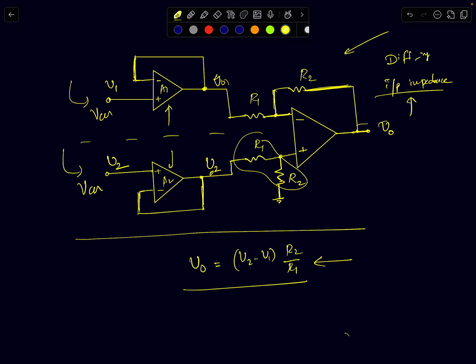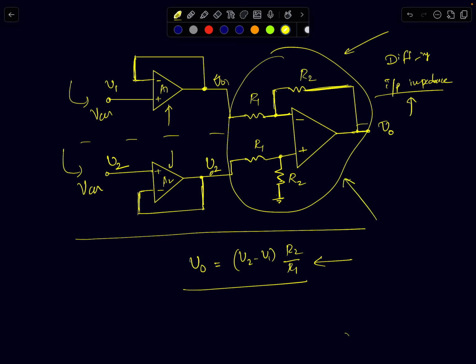But mainly resistor matching is a bigger concern, and you would prefer to have all of them inside a single chip. When you put all of them in a single chip, then gain programmability becomes a challenge. One of you is asking, why not just add a different stage for the gain? You want to minimize as many components as you can, and have the circuit as differentially symmetric as possible. You can picture this stage as a differential to single-ended converter. Until this point, if you can maintain differential nature, we are good. So think of it like that.